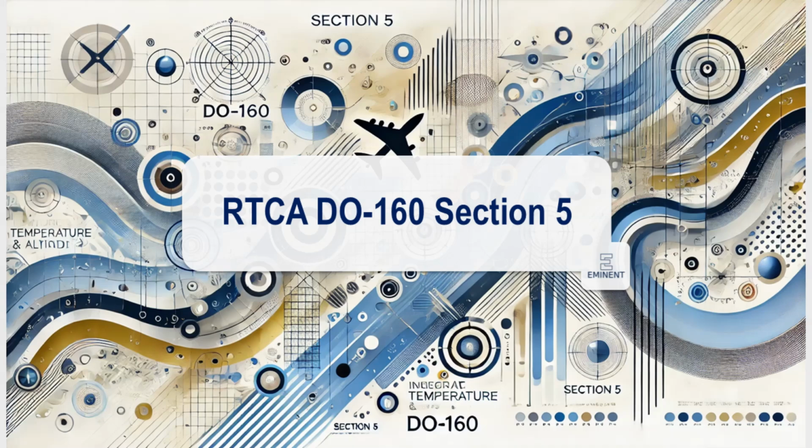Category S2. The standard category exposes equipment to moderate temperature cycles to simulate typical flight conditions. Common failures include cracks in solder joints and stress on mechanical parts due to expansion and contraction. Mitigation: employing flexible mounting systems and using high-temperature solder can reduce the impact of thermal cycling on critical connections.